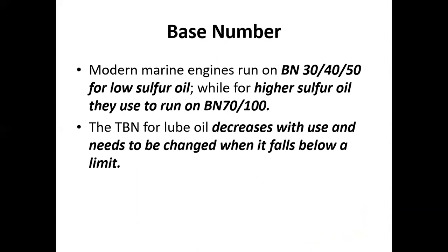Modern marine engines run on base number 30, 40, or 50 for low sulfur oil, while for higher sulfur oil, they used to run on base number 70 or 100. The BN of lube oil decreases with use and needs to be changed when it falls below a limit.